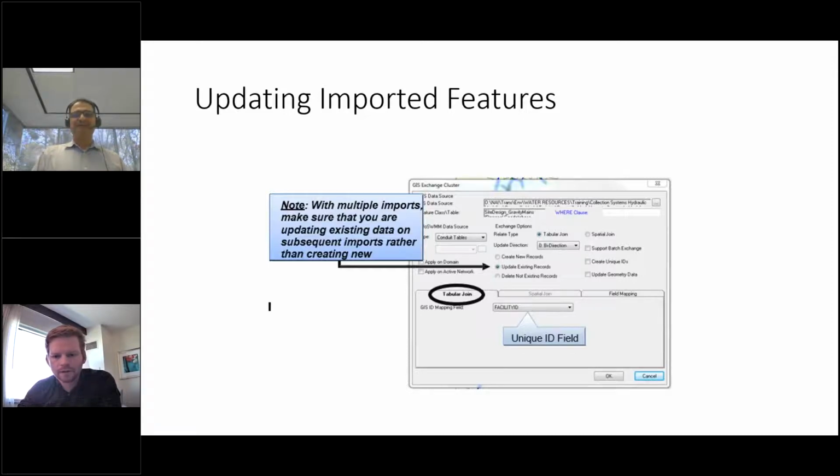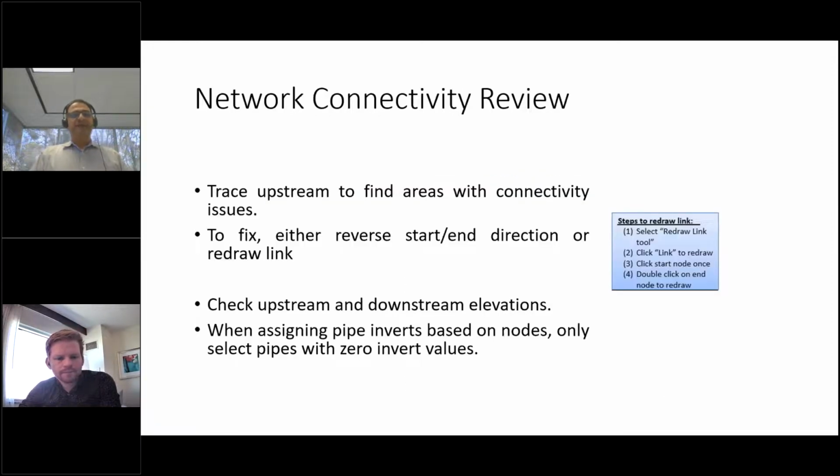So keep going. Okay. Next is a note on network connectivity. You've imported. Obviously, I would strongly recommend, I don't know, there's a way around it, just the junctions first, set up your manholes, and then hopefully you have the start and stop manhole defined in your conduits table in GIS, and this way you connect them correctly as you import the pipes. So import the manholes. If there is ever a question about that, always start with the manholes.